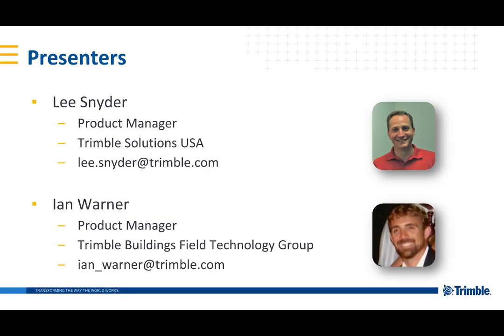Today we want to discuss layout for construction workflows. So I'm going to go through and start in Tekla Structures and show how we can create layout points, how we can export those to share them with the field team. And then Ian will show how those can be brought in and utilized in the robotic total stations out on site or also in a fabrication shop.